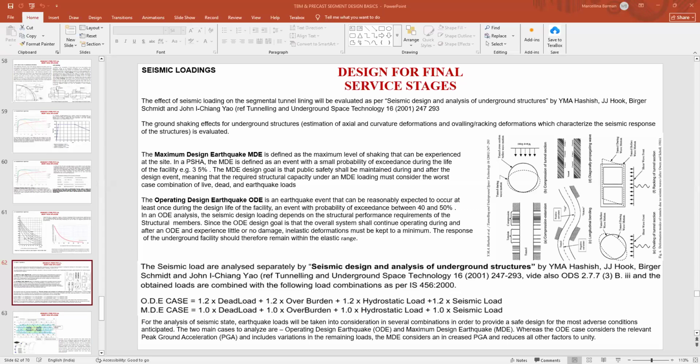Exactly. Because the design we are doing is in a desk study, you have a very limited amount of ground parameters. You have limited knowledge of your ground, and whatever parameters you are considering are in 2D, because you are not considering the whole area. So if you are considering a 3 kilometer tunnel, you are designing per meter cross section. You are not designing as a 3 kilometer tunnel. What is the total variability in the geology, ground condition, building loads, everything? That is taken into account by the partial factor of safety.